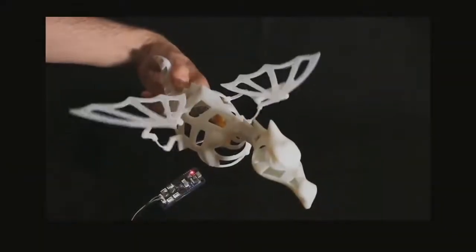They have to assign weights that dictate the relative importance of these objectives. But this is a high-level thing, right? It's still very, very different than coming up with the flexure parameters that would give you this performance. So, all right, when you put all these things together, then you end up with a design tool that allows you to rather quickly and easily come up with a compliant mechanism, such as this one here.